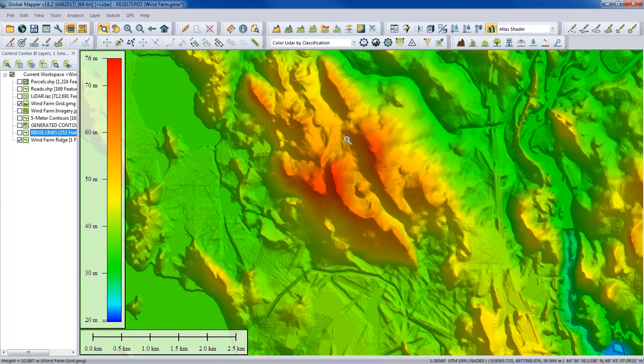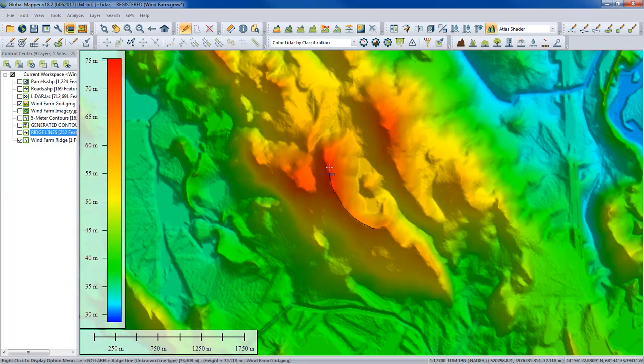And it's prompting me to move. I'll disable that. Use my digitizer. And you can see a little short section. I may have extended it to the end of the ridge, but that's fine in this case. But that line feature allows me to essentially delineate the high points, connecting the dots representing the high points.